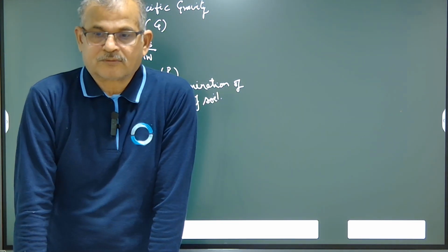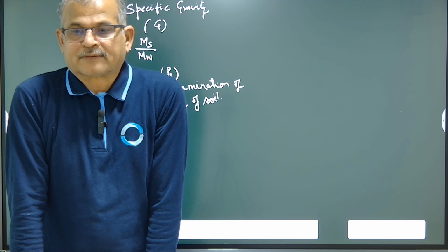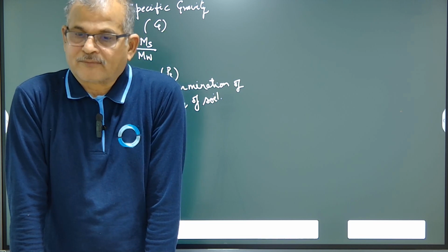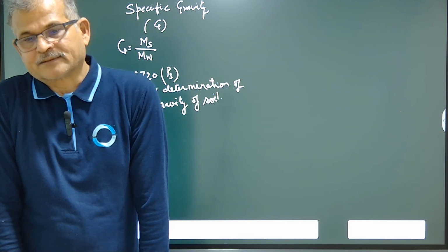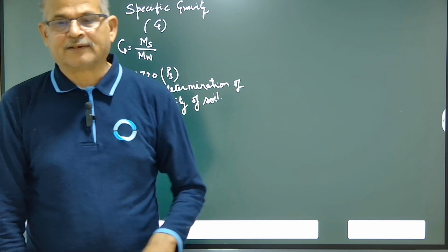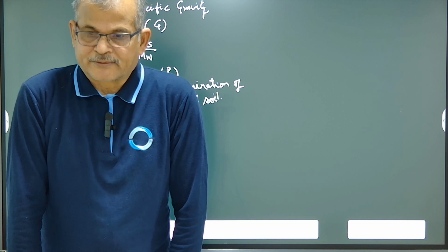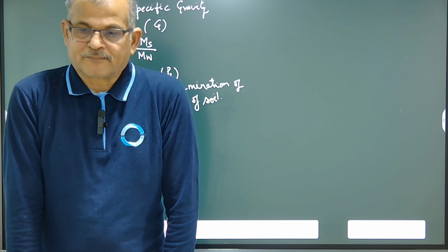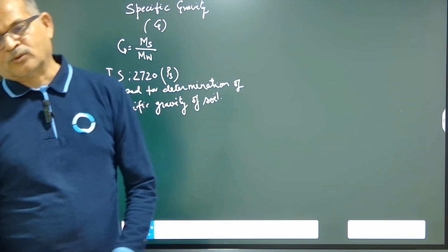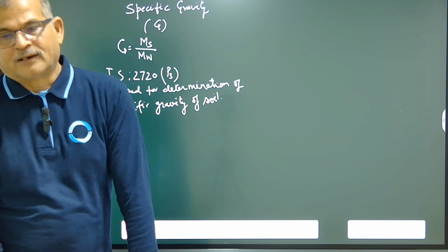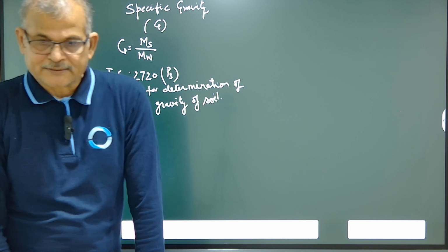In part 2, the quantity of sample required is given. As per part 2, we take 50 gram of sample, then quarter it and take 10 to 12 gram of sample passing the IS sieve, and oven dry it at 105 to 110 degree centigrade.